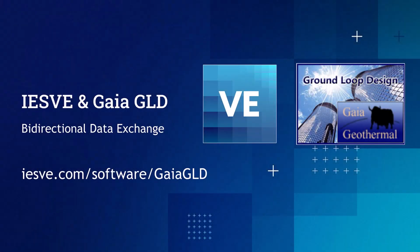That concludes the step-by-step demonstration showing the bidirectional data exchange workflow between IESVE Software and Gaia Geothermal's ground loop design software. As a sign-off note, I would like to say that accurate right-sizing of the building's heating and cooling loads are critical to an optimized and right-sized geothermal heat exchanger design, because oversized heating and cooling loads may result in oversized and expensive geothermal systems. This data exchange between IESVE and GLD should help designers to optimize the overall system design.